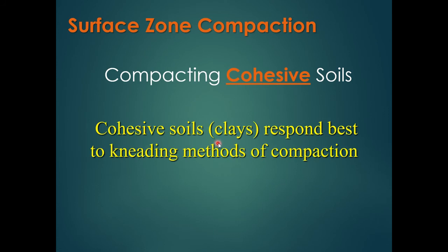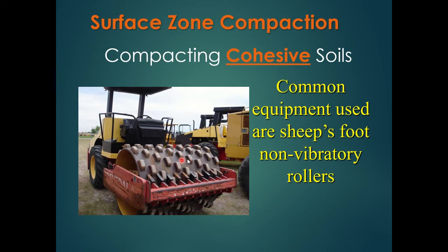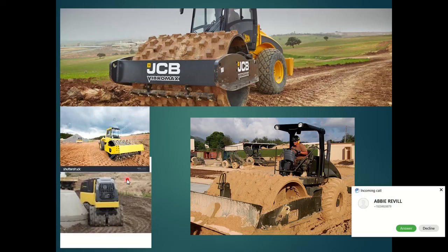Cohesive soils, clay, kneading methods of compaction. Kneading. Sheep's foot, non-vibratory rollers. I don't need any vibration. We need to knead it. Sheep's foot.